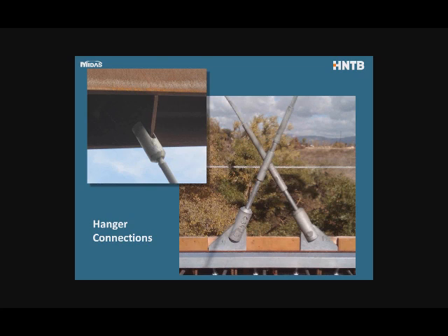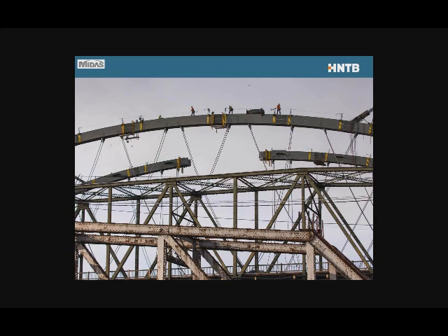At the lower end, shown on the right-hand side of that picture, you can see some turnbuckles to adjust the cable forces. Very simple operation. In this case, for some cables, they didn't even have to unload the cables. They can just turn the turnbuckles. For the highly loaded cables, you'd need to come along, unload the cables, and then turn the turnbuckle. But very quick and simple connection. This also works for the larger size bridges, and this is really the traditional method of hangers in the US at least.